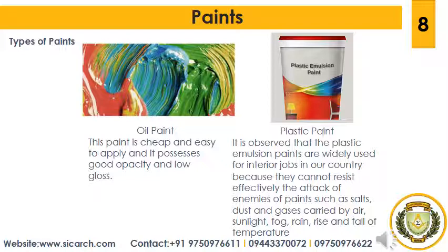So these paints allow moisture to evaporate through minute pores, but even then it is desirable to allow 4 months, preferably 1 year for moisture to escape from fresh masonry and fresh plaster. So the next is about the nature of the surface.